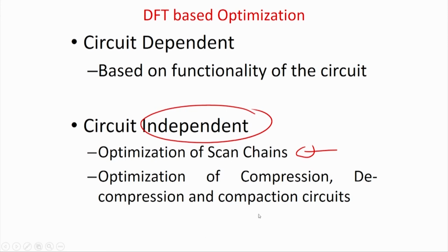That is another way of asking how you can compress the ATPG test patterns, so that the additional compaction and decompaction circuits you put in, which help in compressing the test patterns and compacting the output response, do not become too large. A lot of work has been done in this area, but it is more related to coding theory, etc. So in this lecture we are not going to highlight that; mainly we will look at the scan chain. As I told you, almost no circuit at present can be built without a scan chain, so most test engineers emphasize optimization of scans.